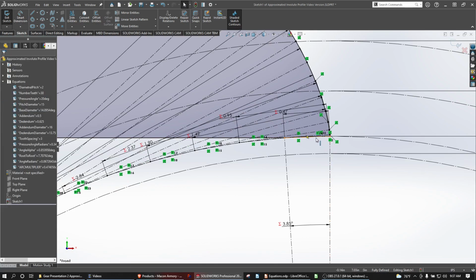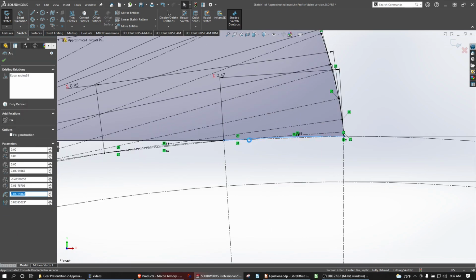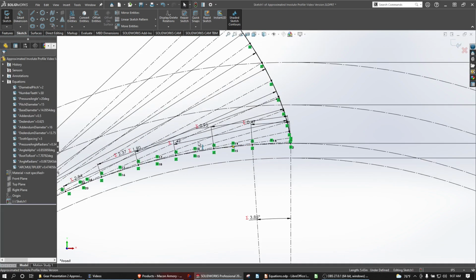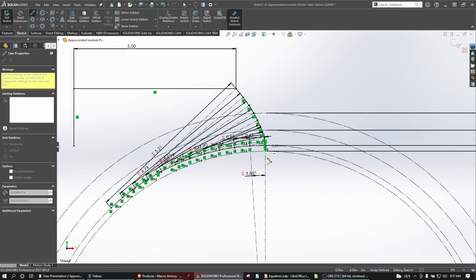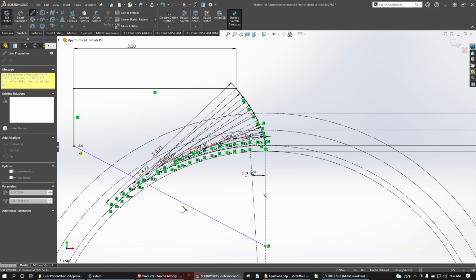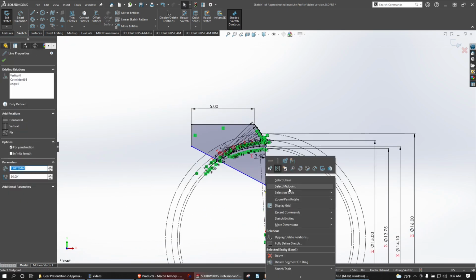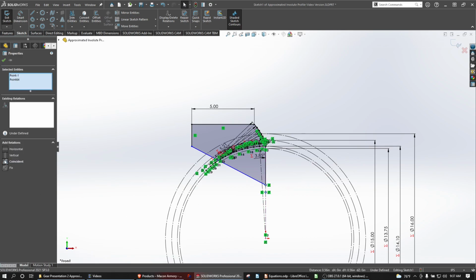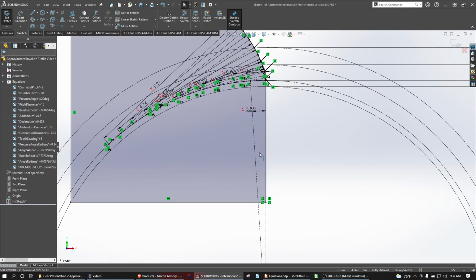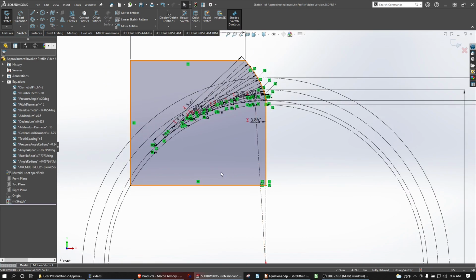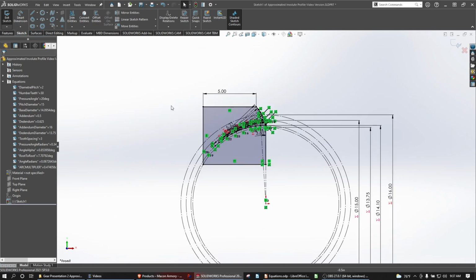You know what? I should actually just get rid of this arc and get rid of this thing. We want this tooth to be a little bit deeper than it is, so we're going to come down here and select this midpoint. There it is. Coincident and horizontal. So our tooth will go deep. And you're probably looking at this thinking, what a strange way to define this. But I hope it'll come a little bit clearer as we go.